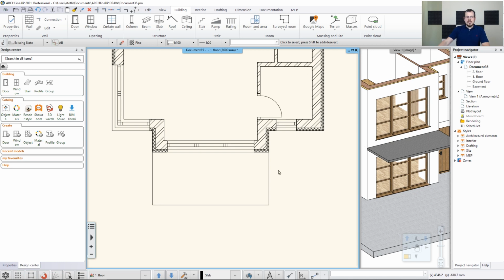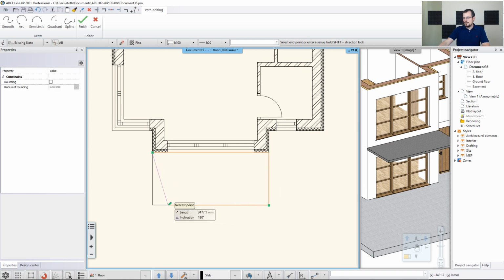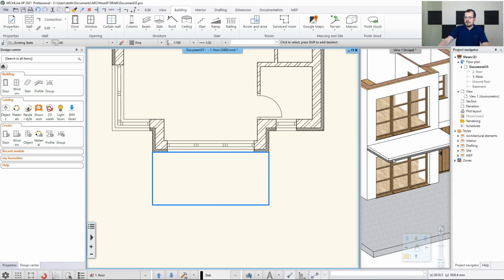And now, one trick I would like to do, I'm just going to resketch what I already have. So I'm going to click slab in sketch mode, and drag over the part of the drawing that you already have at hand and hit enter. And now you ended up with a two-layer slab. You could have done this in one step, but what you need is that piece of slab should be extended outwards to 100 millimeters. How do you do that?